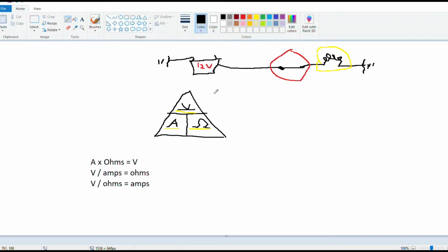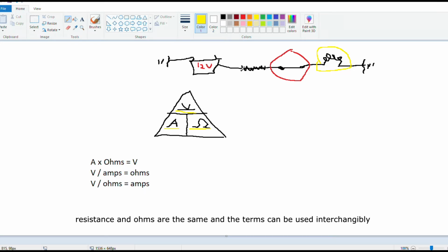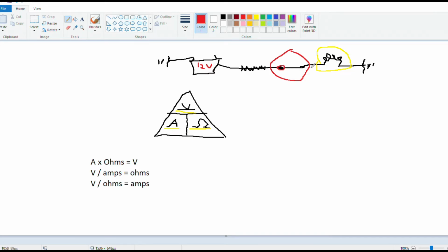So something else that we probably will have seen before is you turn the headlights on and they're dim. And this is the basics of electrical diag. So the reason they're dim, we can refer back to Ohm's law here, is you have resistance somewhere in the circuit. Whether it's at a switch connector, at a bulb socket, or a bad ground, it can be somewhere in there. But let's just say we've got a green wire, because that's something pretty common that you'll see. So you've got resistance here.